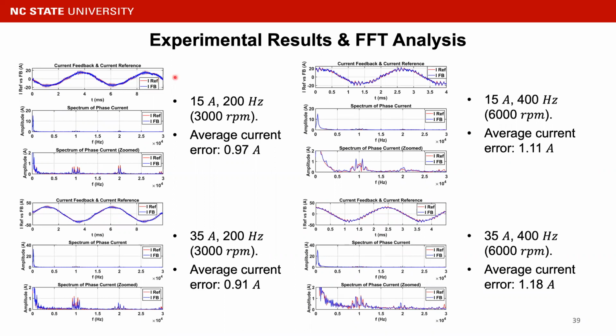And on the voltage sensing side, because we need to sample the PWM voltage for the input of our motor model, this process is done in 2 steps. We have a dedicated circuit to sample the logic level of the PWM voltage.